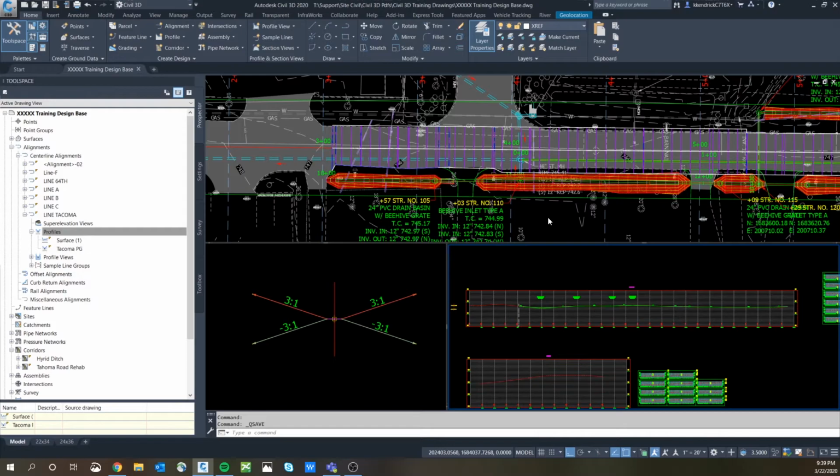I don't have my autosave on real frequent because if you're computing something big, if it's regenning a large corridor and you try to autosave, it tends to lock your computer up doing both things at the same time. I have mine set to 45 minutes, so whatever you're comfortable with, but it's kind of a catch-22.